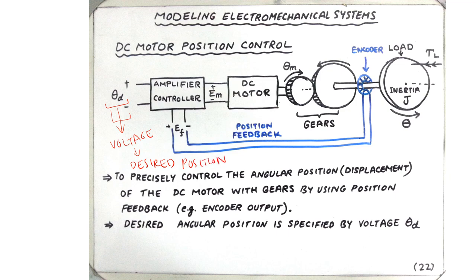In the context of the DC motor position control and their application, they often come with the gear system, or we attach a gear system with the motor, because in the position control application, speed is not a requirement.